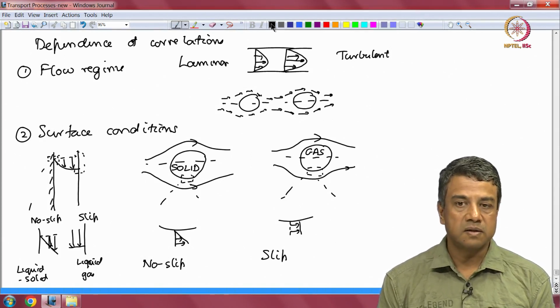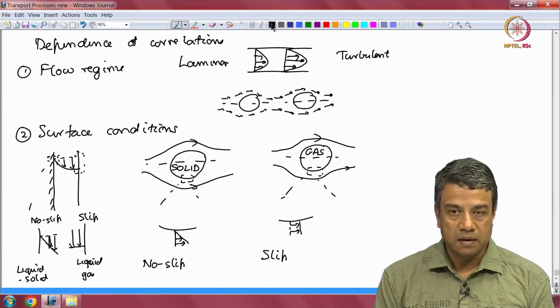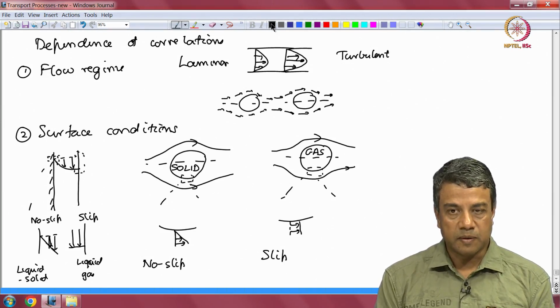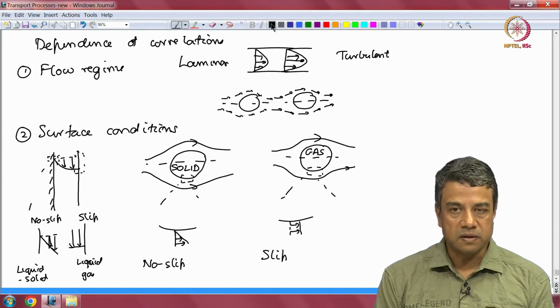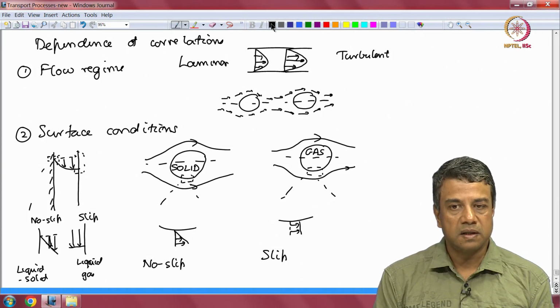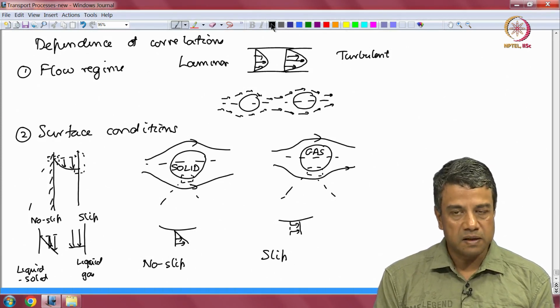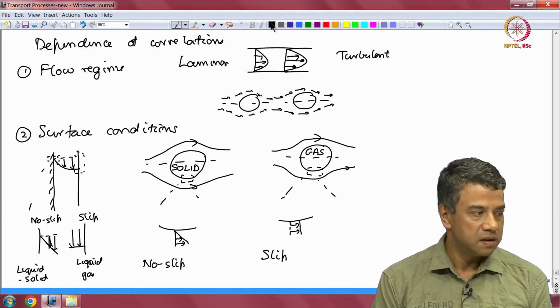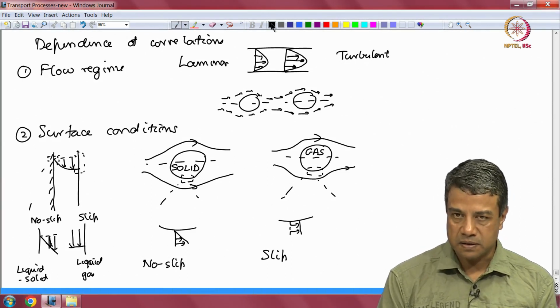So, there is no fluid flow relative to the solid either in the tangential or normal direction, either perpendicular to the surface or parallel to the surface. The relative velocity between the fluid and the solid parallel to the surface has also got to decrease to 0. The perpendicular velocity is of course 0 because the surface itself is impenetrable, that is the definition of the surface. So, therefore, the perpendicular velocity is necessarily 0 at any interface.